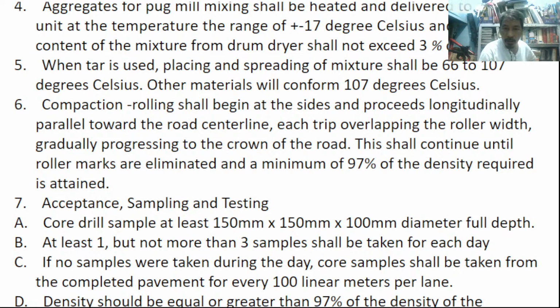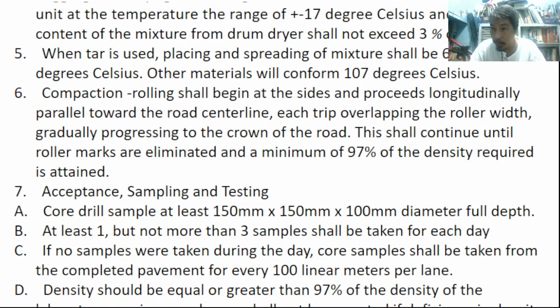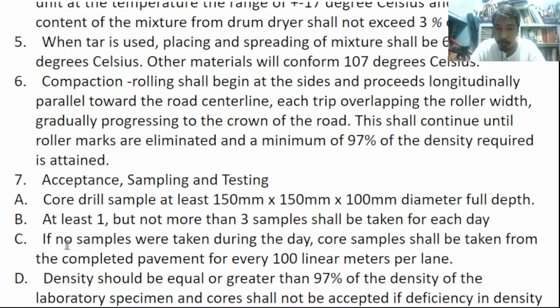So that means every project engineer wants to have a sample during the day, for each day, so that you don't need to drill to the actual pavement. You don't need to drill to the completed pavement. You need to have a sample taken prior to this. Okay, so because you will repair it. You will repair it after you drill it, testing the samples.